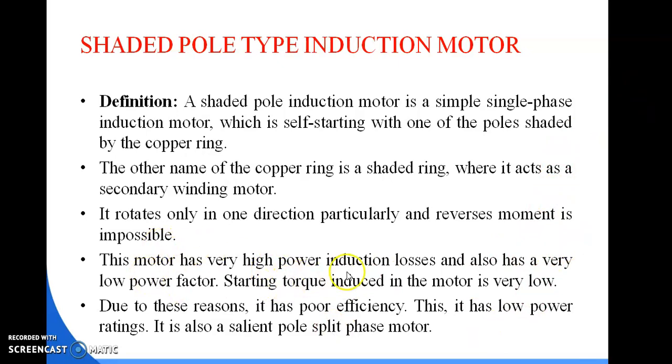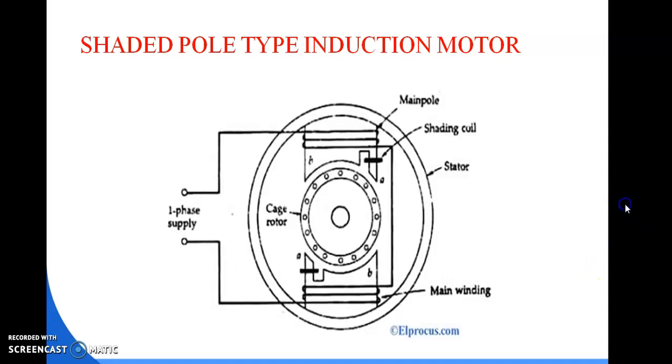This motor has very high power induction losses and also has a very low power factor. Starting torque induced in the motor is very low. Due to these reasons, it has poor efficiency. It has low power ratings. It is also a salient pole split phase motor.